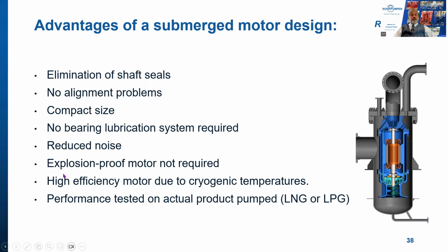So this one might surprise you. An explosion-proof motor is not required. And I can see some of you would think, well, surely LNG, LPG, this is flammable material. But yes, it is, but only in the presence of oxygen. And with this design, there's no oxygen and no possibility of oxygen getting into the pressure vessel.